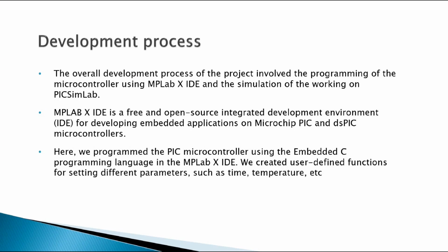Here, we programmed the PIC microcontroller using the Embedded C programming language, wherein we created user-defined functions for setting different parameters such as time, temperature, etc. Along with this, we used some user-defined libraries for interfacing the peripherals such as LCD, buzzer, matrix keypad, etc.